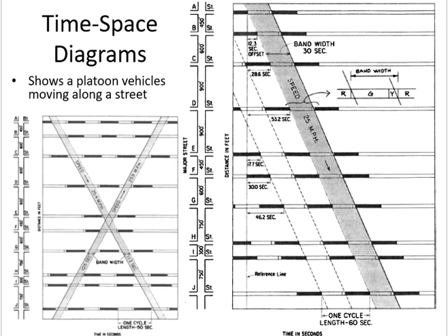You are prioritizing this direction, and what will happen to the other direction? I don't care, because these are minor streets. So this is done when you have a series of intersections close to each other on a major street, and they are crossed at all intersections by minor streets. All of them are minor.